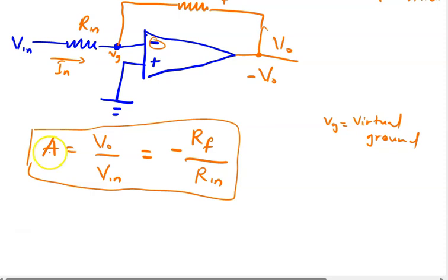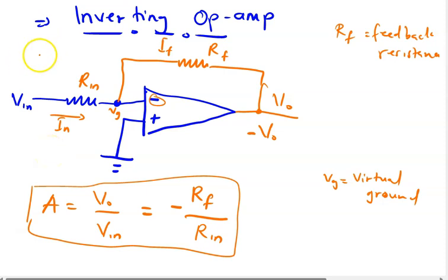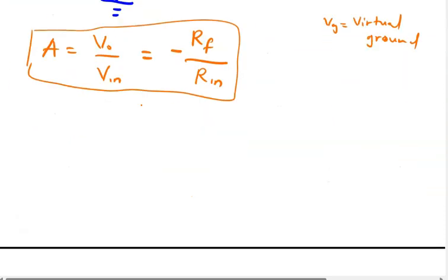So this is an inverting op amp. Why is it an inverting op amp? Because we have a voltage and the input resistance connected at the negative side of the op amp. Take note, they can interchange the sign. The negative can come here and the positive can go there. Do you get it? And once it changes, don't be confused.